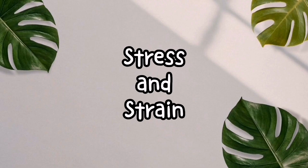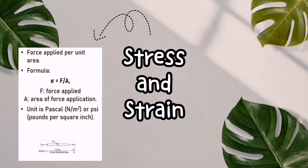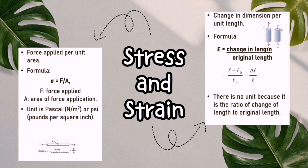We continue on the stress and strain part. Stress is force applied per unit area, also an applied force that tends to deform a body. The formula is stress equals F over A, where F is the force applied and A is the area of force application. The unit is Pascal or PSI, pounds per square inch. Next, strain is the change in dimension per unit length. The formula is strain equals change in length over original length. There is no unit because it is the ratio of change of length to original length.